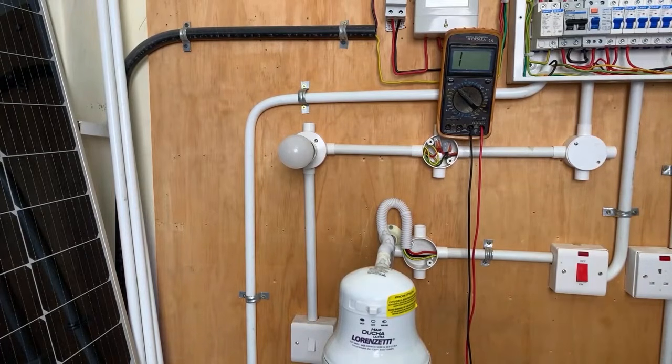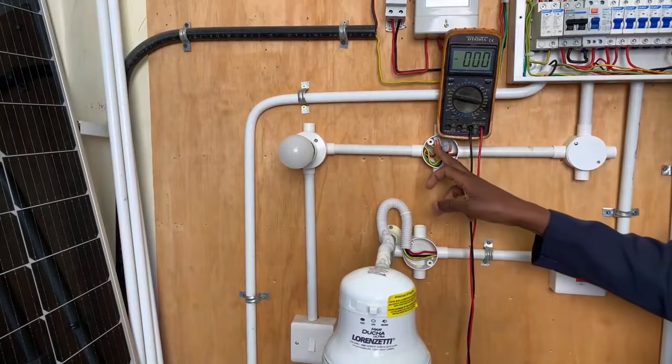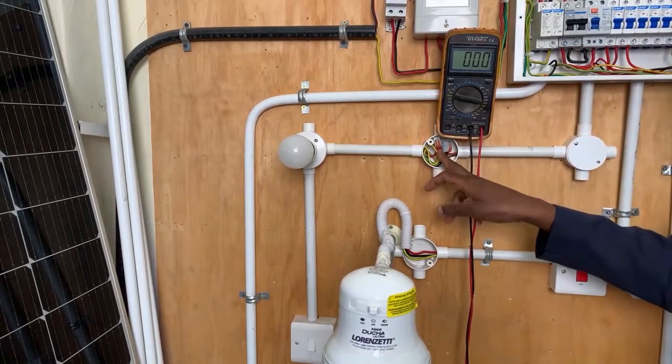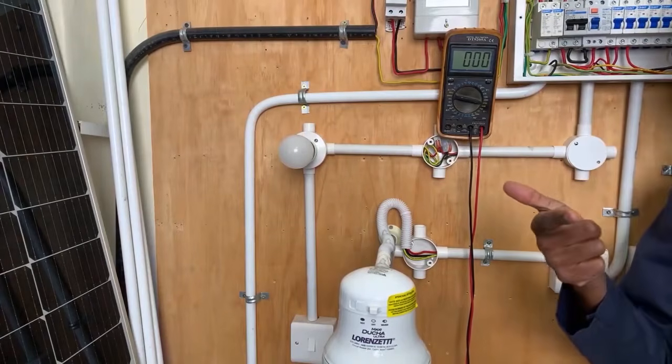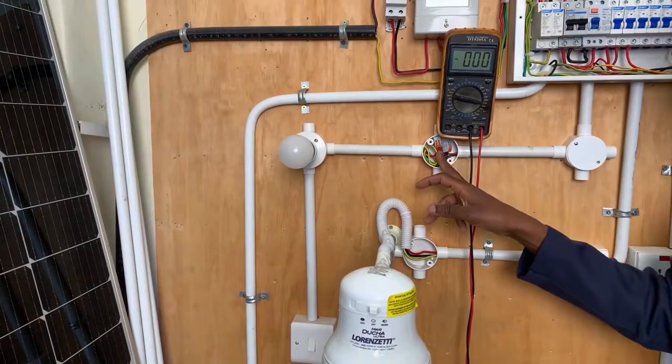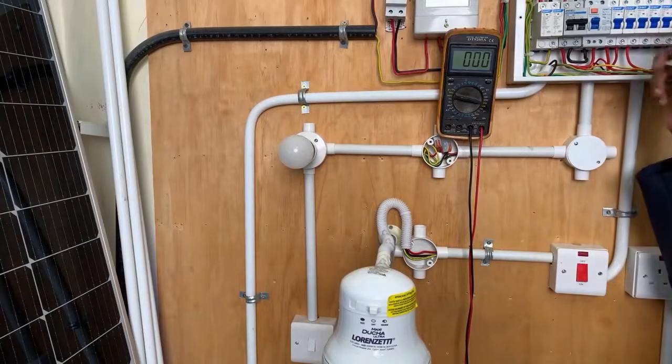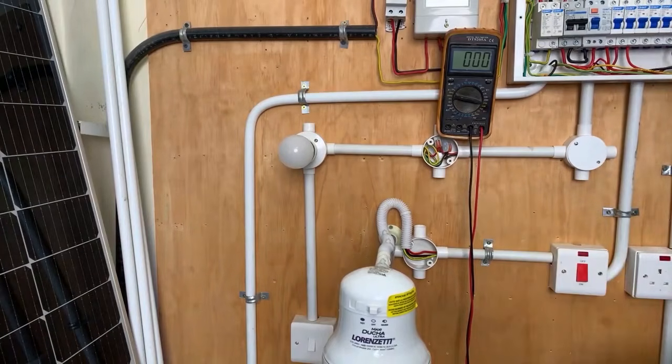So if you allow me, of course, I'll be very careful not to switch the circuit breaker back on while the short circuit is still there, until we sort it out with a multimeter. So do you give me a go ahead, top bosses? If I get a go ahead from you, definitely I'm going to do that. I was saying, if we short circuit the line and the neutral at this point, we can demonstrate how the MCB tripped, assuming that MCB is okay. And then after we sort that one out, we test and then turn the MCB on, and then put the circuit, the lights on. So we go ahead and do it.